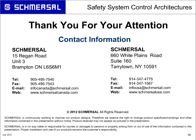It's a couple amps, no inductive loads or motors. But that's not the normal situation you run into. You're shutting down motors, you're shutting down hydraulic pumps, you're doing different things on machines that you have to use external mechanically linked contactors, and because they become an extension of that safety circuit, they're required to be mechanically linked, and you need to feed those back in to monitor their functionality. And then if you do not do that, you're not achieving the control category you set out to achieve.